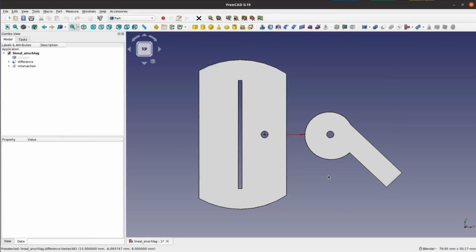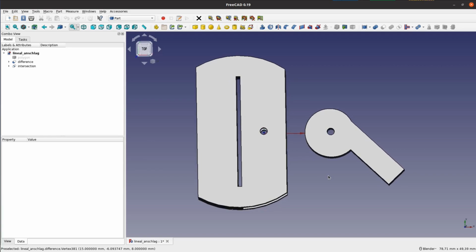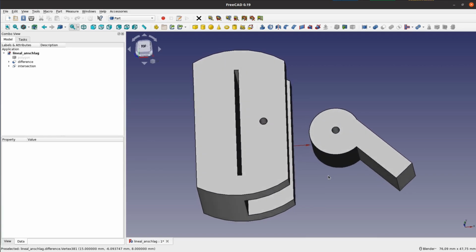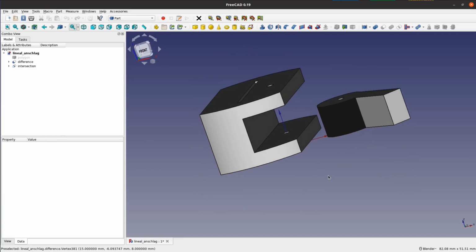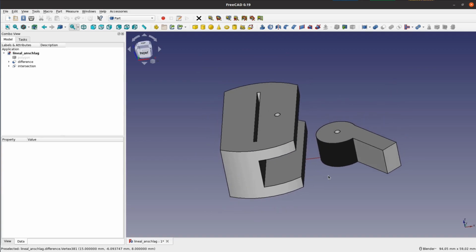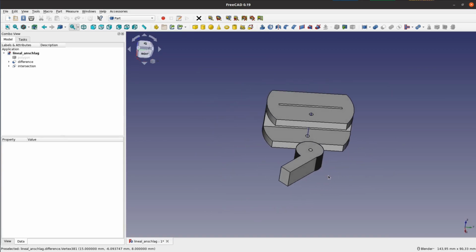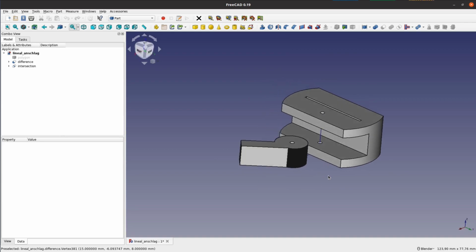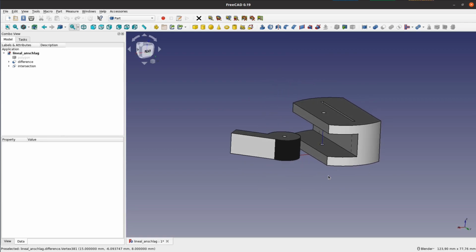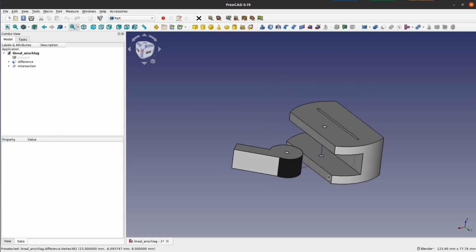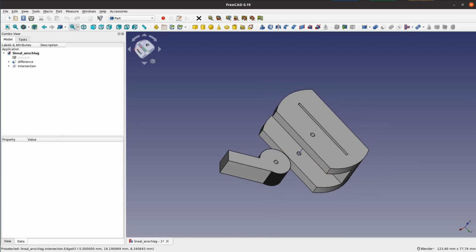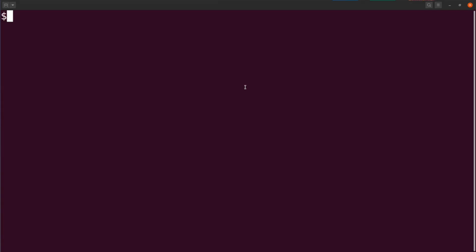If you're downloading a file from Thingiverse, you could be lucky and have a file that has the extension .scad. This is an OpenSCAD file, and if you don't want to use OpenSCAD on your computer, the files can most of the time be directly opened in FreeCAD. Here we look at a small 3D print to convert a ruler into a marking gauge. It is important that the OpenSCAD import depends on a Python module.